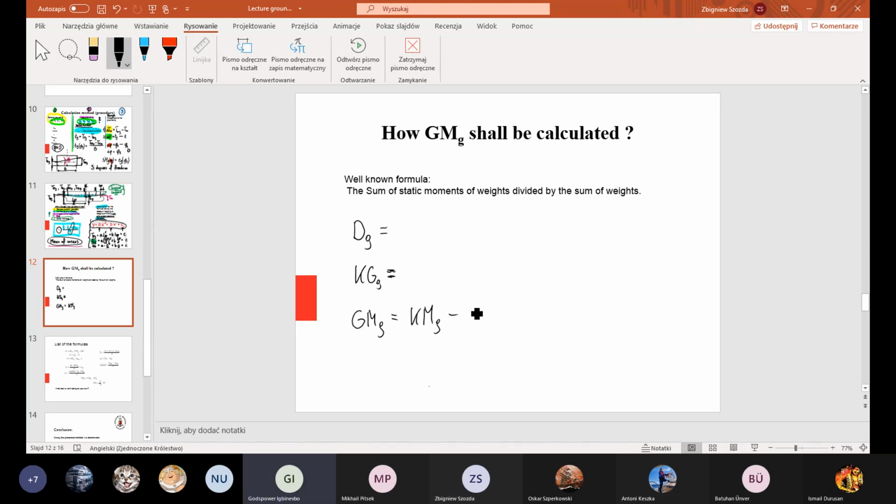Yes, so we subtract the center of gravity after grounding from it. So that's how we get the GM after grounding. Can I ask a question? We need hydrostatic particulars, hydrostatic table to read KM after grounding. Yeah, fine. So, very good. I think God's power, you are correct. But now we shall go to details. How to calculate displacement after grounding.